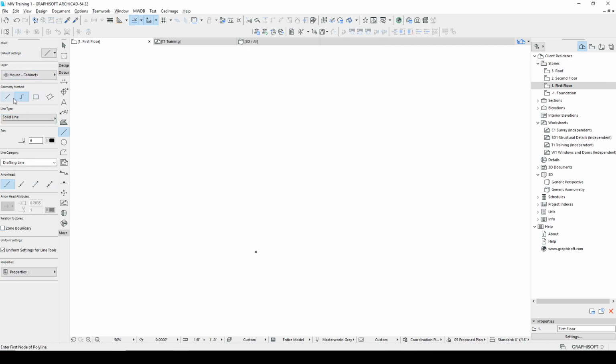I have a single line, I have multiple lines, I have a rectangle, and I have a rotated rectangle. And I'm going to go through these really fast. They're assuming you've used other computer programs. I mean, these are really fundamental. These aren't going to feel too strange to you, but a line is click, click for a line. I never ever use this. I don't want to have to start the line again and start the line again and keep going. I always use the chain line, and it's a double click to stop.